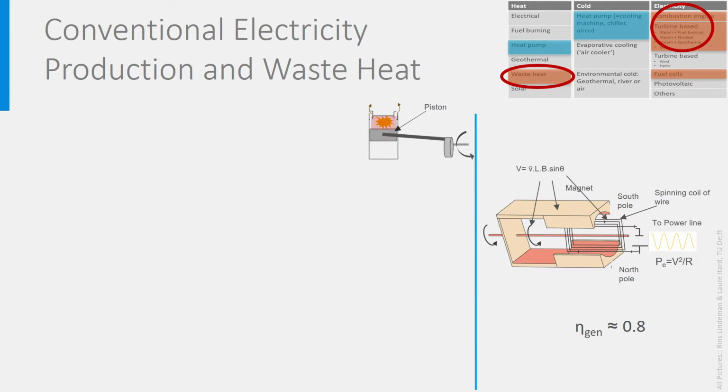In a combustion engine, fossil fuel or biogas is burned directly in the engine, making a piston move. The piston is connected to the rotor of the generator by a rod, and as the piston moves, it rotates the rotor. This is exactly the same principle as the gasoline or diesel motor of a car. When fossil fuels are used, all the fumes released to the outdoor air contain CO2 and harmful combustion products. In practice, the efficiency of such a combustion engine is between 0.35 and 0.45.